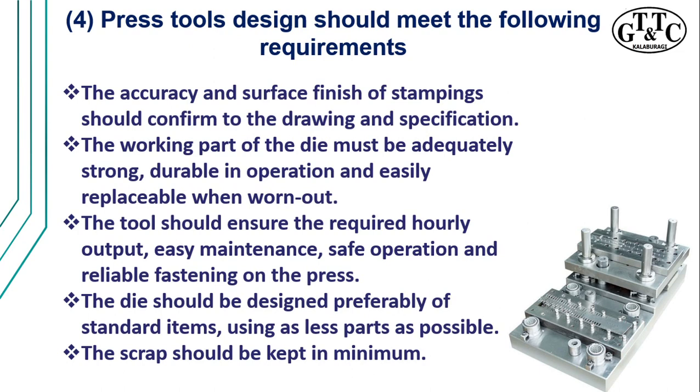Then the next one is the tool should be designed with standard items, hardware and the standard die set so that the manufacturing time can be minimized. With the present competition, it's very important to focus on the time management of manufacturing a tool. The lesser the time, the better the production or the business of tooling with the customer.